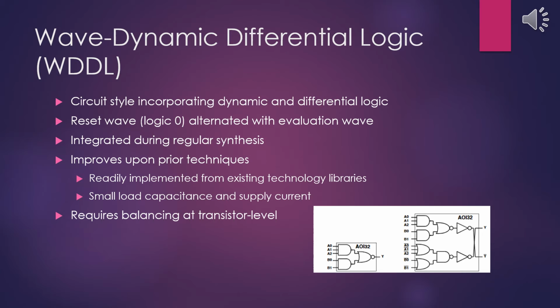Another type of layout is called wave dynamic differential logic. This circuit style is both dynamic and differential. A pre-discharge reset wave is alternated with the evaluation waves to allow for the dynamic logic. It is integrated during regular synthesis and improves on prior techniques by being easy to implement and using existing technology, and using a small load capacitance and supply current. This means that the signals are stronger and that it requires less power. The load capacitances must be matched so that the amount of capacitance charged stays the same. The diagram on the right shows the difference between a static CMOS implementation of an inverter cell and a wave dynamic differential logic implementation.